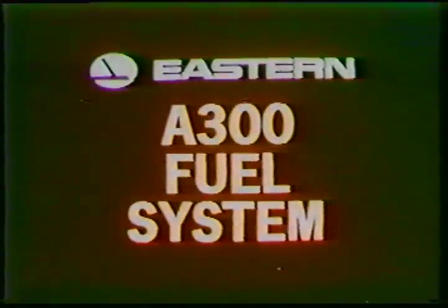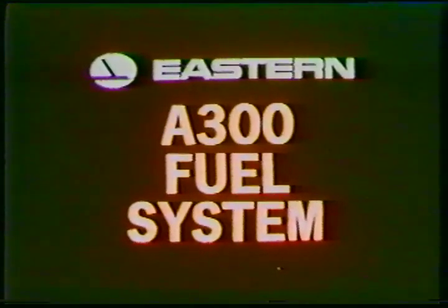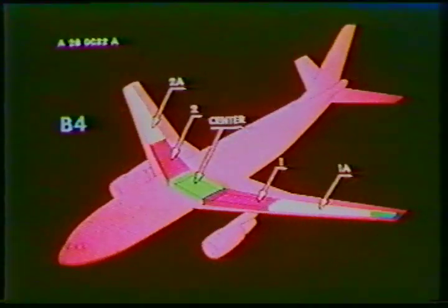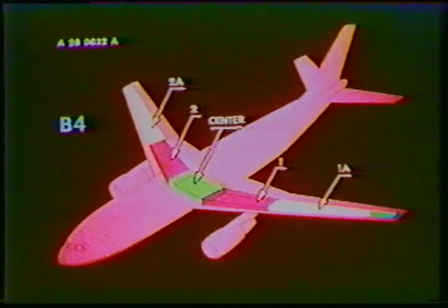Eastern Airlines presents the A300 fuel system. It is a fairly simple system, easy to understand, and automatic in operation. 5 fuel tanks supply both engines and the APU. The 5 fuel tanks, numbered from the left wing to the right wing, are 1A, 1, center, 2, and 2A, and are integral parts of the wing structure. The vent surge tanks located at the wingtips are used to vent the fuel tanks.